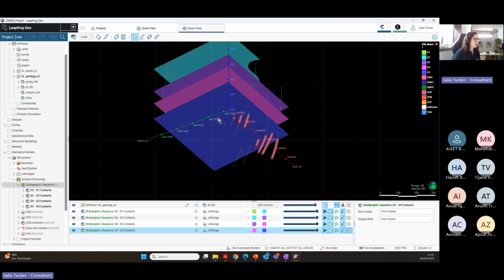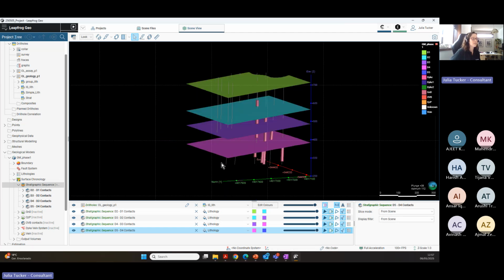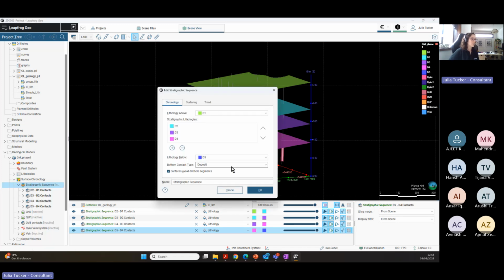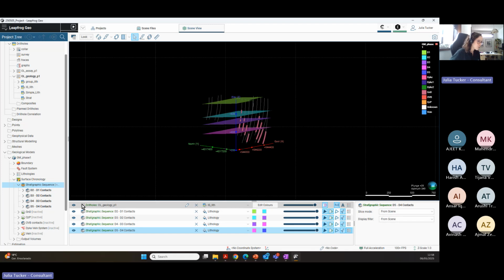And this way it goes on. So right here, I should have just the D5 color, because this way I will not get anything that is unknown. If you have any kind of unknown basement, you can also add it here. When we were doing that, you would just input this as unknown lithology below. So just clicking on the OK, now we have all of our surfaces done.